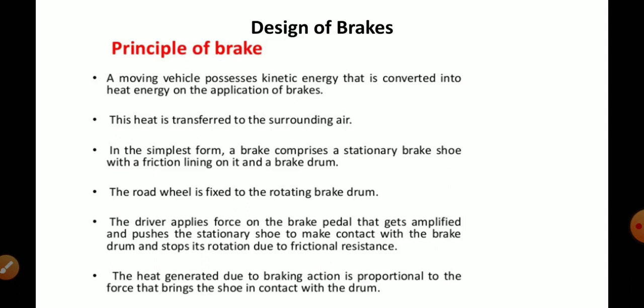In the simplest form, a brake comprises a stationary brake shoe with a friction lining on it and a brake drum. The road wheel is fixed to the rotating brake drum, and the driver applies force on the brake pedal. The applied force gets amplified and pushes the stationary shoe into contact with the drum and stops its rotation due to the frictional force between the brake linings and the drum.